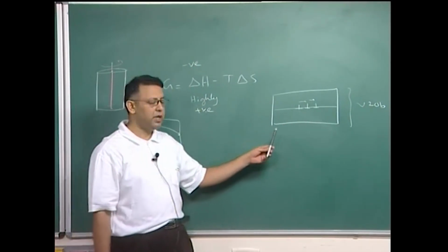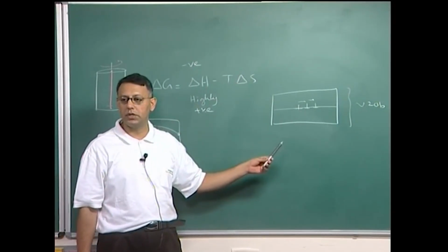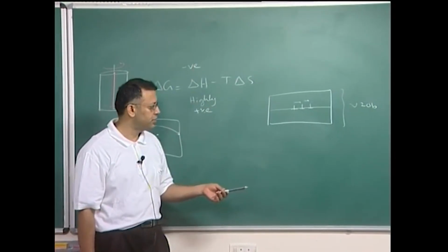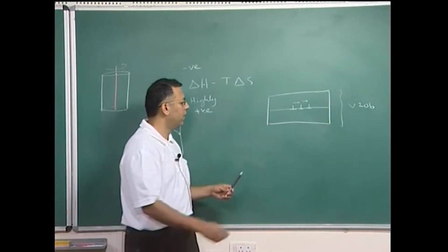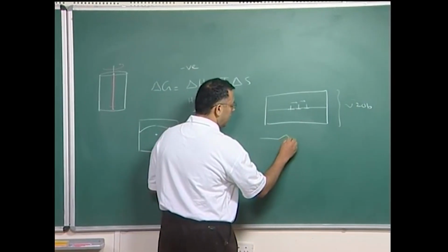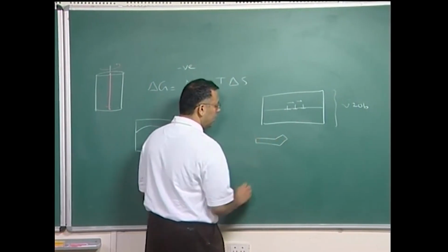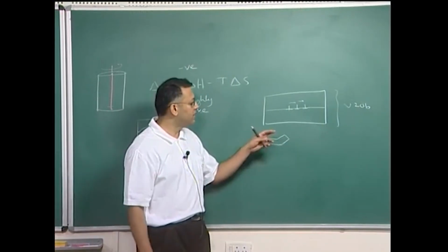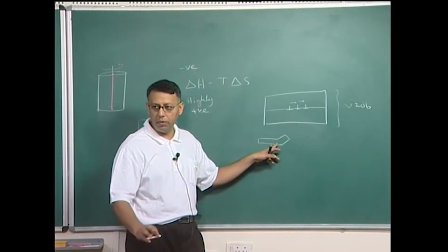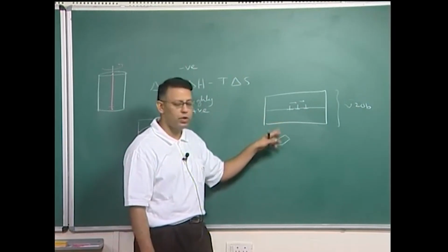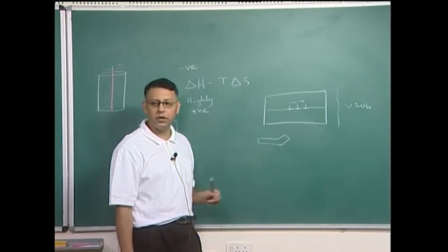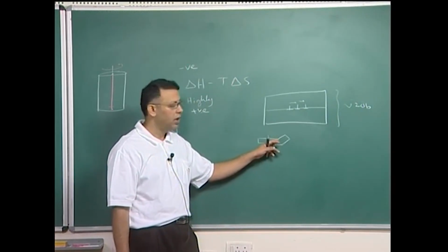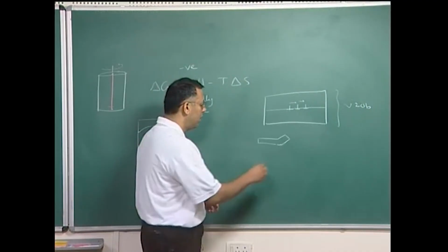Because what is plastic deformation? Plastic deformation is deformation in the absence of externally applied forces. Here, even in the absence of any externally applied forces, you see, and I am exaggerating the picture here, the crystal actually bends because of the dislocation which I just showed you. And this bending is permanent. I do not have to apply any external stresses. This is merely because of the presence of the dislocation. It is permanent, therefore it can be called plastic deformation.